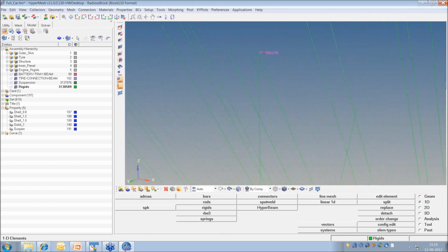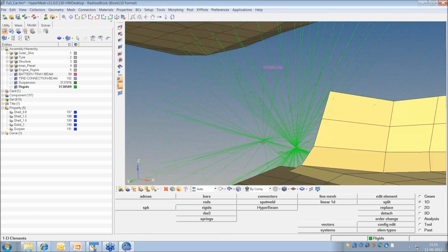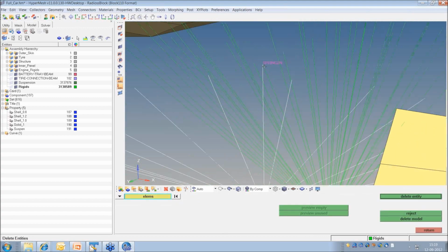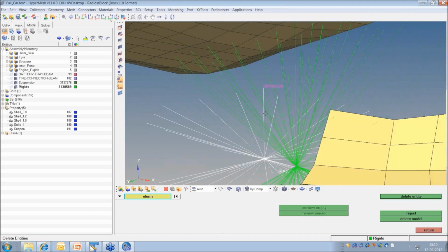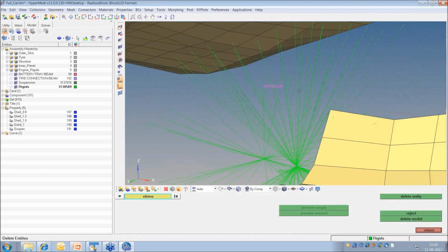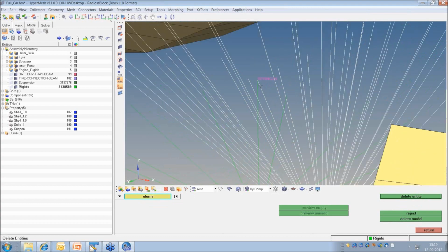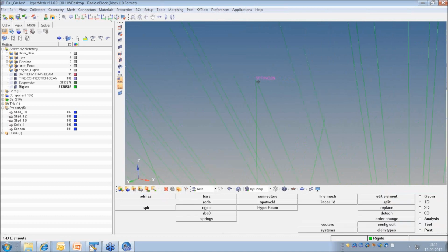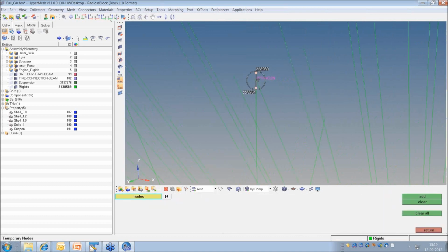But if you see it here, you have one leg which is coming from this rigid, and you have other leg which is coming from the other rigid. They are not equivalent, so there are two separate nodes over this location, and in between that we have this zero length spring, which is a type 8 spring. So this is regarding the creation part.